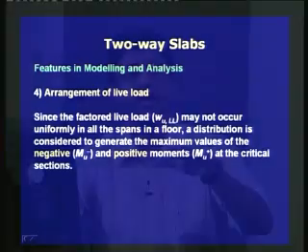When we are applying the gravity load, we have to be careful whether the live load should be placed uniformly or not. The dead load can be placed as is given for the member sections, but the live load may not be uniform throughout the span and for the different spans in the equivalent frame.